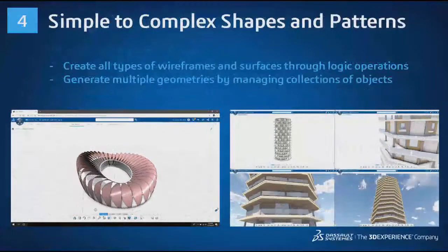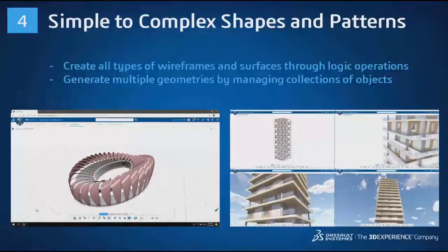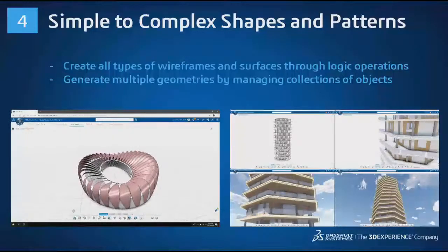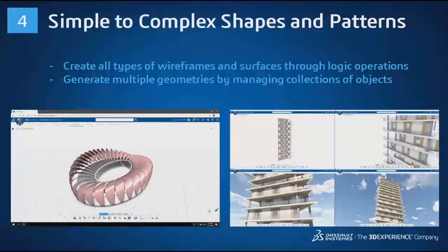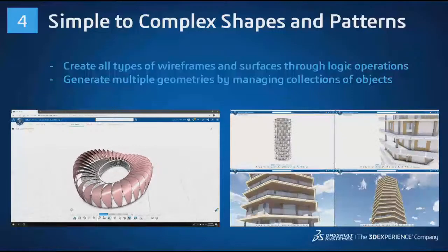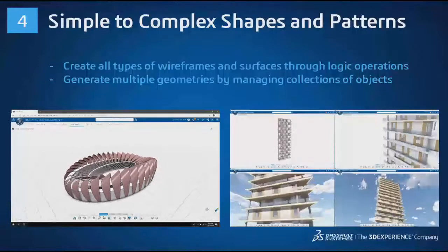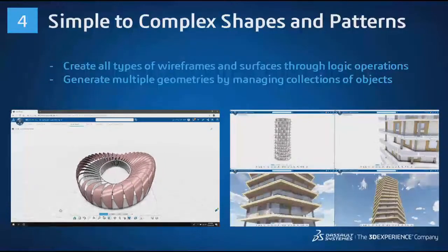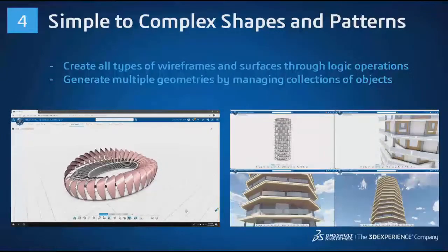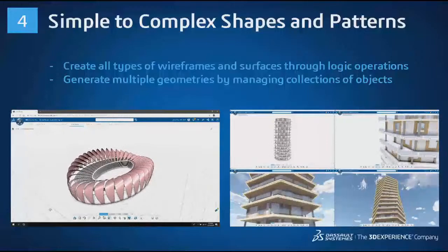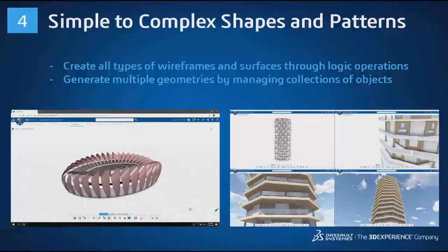X-generative design is also a way to generate both simple and complex shapes and patterns. You have access to a wide range of wireframe and surface geometry, volume geometry that allows you to do booleans and other volumetric geometric operators. You can generate multiple geometries with these operators to create collections of geometry that are manipulated either as a group or individually.